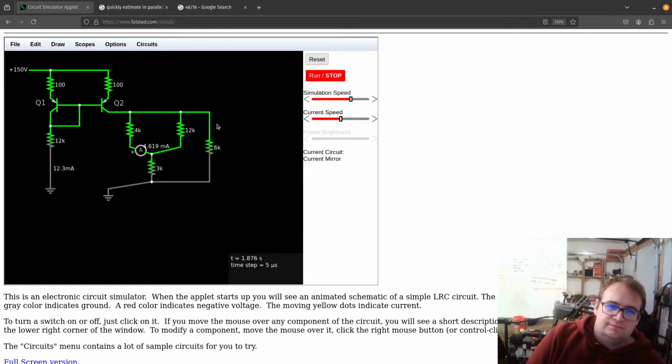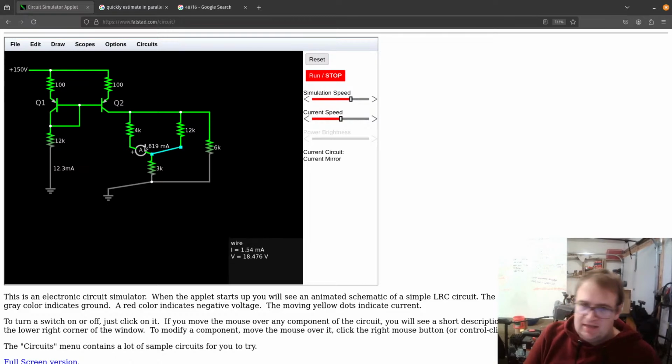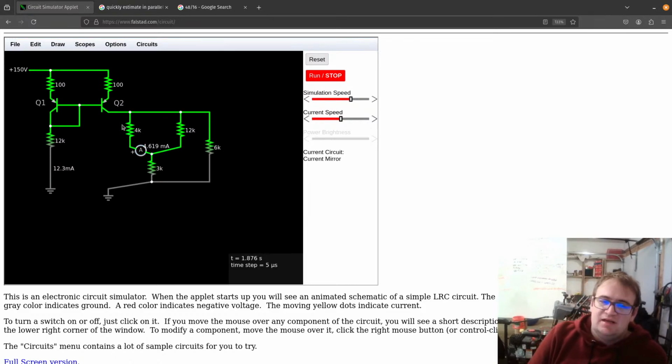So that's how we get to this 36 volts there. Now, that's going to be the same on both. So 3 kilo ohms will be passed here, 3 kilo ohms there. So half and half will go. So 6 milliamps through here. That means, again, I was right at this point at least, about 1/3 of that will go through here, and 2/3 of it will go through here. So I got that.